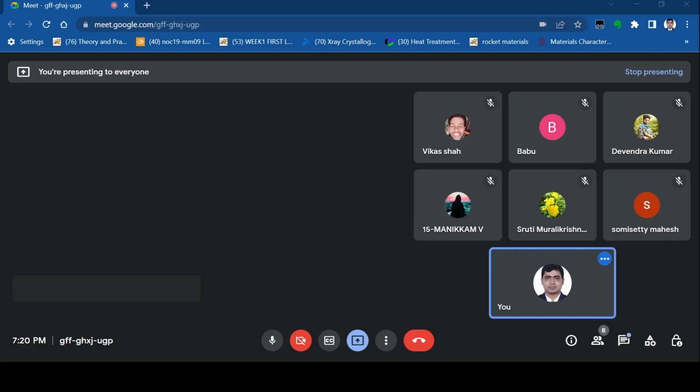You get the value of this R star, that is minus 2 gamma SL by delta GV. So what is delta GV? That is also delta H delta T by Tm. This also you remember, important question. This is the latent heat of fusion, delta HF you can write. This is the undercooling and this is the melting point, or any transformation temperature that has been given. Like for suppose solid, there is one transformation temperature that may not be the melting point. So there you have to use the transformation temperature, T melting or T transformation.